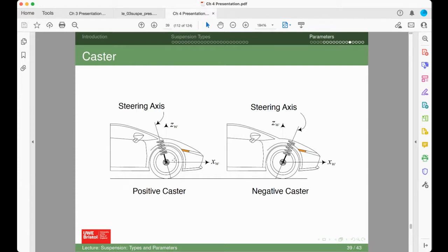But they actually had an interesting setup. A lot of things were hydraulically controlled in that vehicle, including the pneumatic suspension. But they also had active control of the steering. So instead of relying on caster to provide the self-centering, they used the hydraulic system to actually generate the steering there. So the vehicle, when stationary, can actually steer its wheels by using the hydraulic system. Like I said, it was an unusual setup.